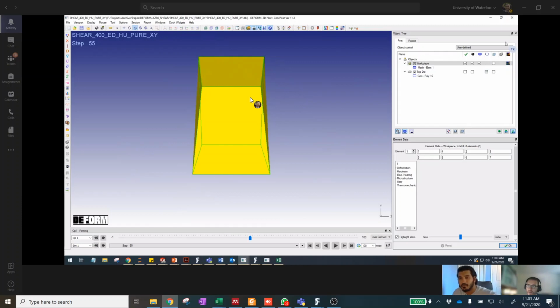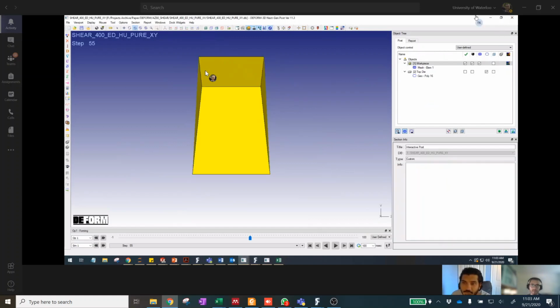Actually, this really is a two-dimensional simulation that you're trying to run. You don't want the thickness direction, but you need it because it's a three-dimensional element that you're using. I either constrain this direction on both sides or unconstrain it and see what the results are. Off the top of my head, I don't know. Your deformed shape in the 2D plane looks right, but you're having 3D stresses induced because you have this hourglassing shape. I'm going to constrain that right now. We can run this again.